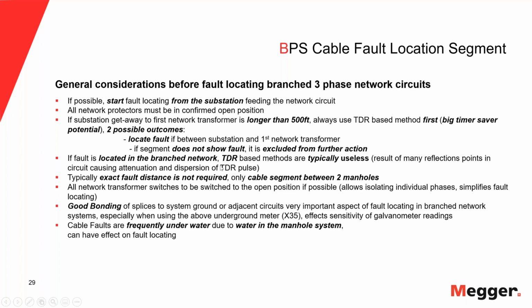Okay, so also what's important to recognize in these type of networks, we don't need to know the exact fault distance, because we're looking for the faulted cable segment between two manholes. So the distance is not that critical. And what's also important is, obviously, if we can switch the transformers to the open position, we should always try to do that, because that allows us to isolate individual phases in the system.